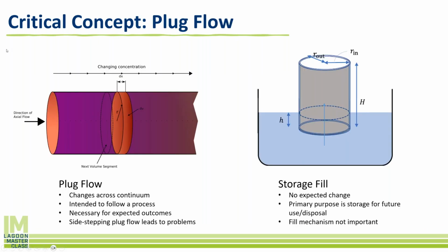One big concept that's important to understand with the wastewater lagoon system is that it is a plug flow system. It is not a bucket that you fill, you let sit for 20 or 40 days and you come back to it. That's not how most lagoons are operated. That's more storage fill. In those cases, you don't want any treatment to occur, and what you're trying to do is just hang on to the water for some future use, whether that's irrigation or disposal or discharge at some other point. That's not how lagoons are operated. It's not a batch, you fill the bucket and you're done.